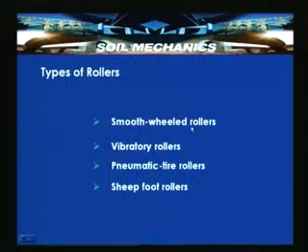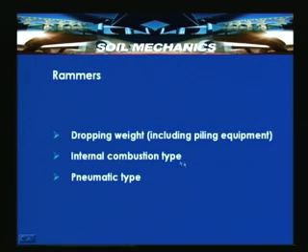So, the types of rollers, if you look into it, are smooth wheeled rollers, vibratory rollers, pneumatic tire rollers, and sheep's foot rollers. Then there are the rammers, which are dropping weight, including the piling equipment, internal combustion type and pneumatic type. These are the different rammers which are used in the compaction field.